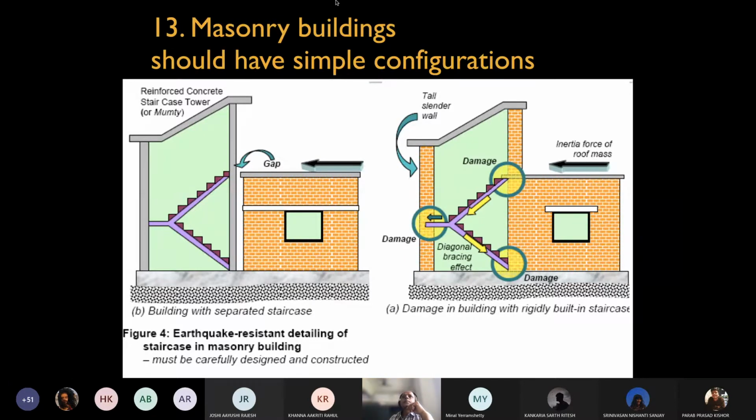Okay. But there were many earthquakes which were studied, and it was noticed that particularly in the tall buildings where the only way of coming out was through the staircase, maximum collapses and deaths have happened in these staircases. So when we are designing the staircases, it's very important to understand how earthquake affects these staircases. Most of the time, even in a masonry structure, the staircase doesn't follow the plane of the slab. So the stresses which are transferred onto the staircase affect the corners, and those corners which are marked in the diagram on the right form the vulnerability. So many times the staircases are the ones which fail first. They are not carefully designed.